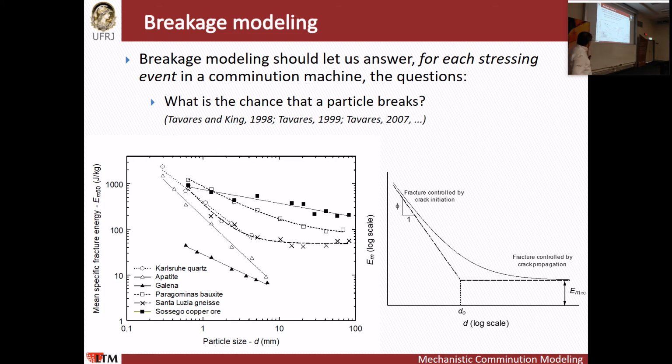That's quite obvious. All the comminution laws more or less cover that. But what is interesting, I believe, is that it's not a single law. It's not a single slope. And further, for some materials, it actually becomes constant here. As we know from school, second or third year mineral processing, we talk about Kick's law. Yes, indeed, Kick's law is very often valid, because for coarse particles, sometimes their strength becomes nearly constant. On the other hand, for some materials that is not quite true. Should we concern ourselves about that? Maybe, but we can measure. If you can measure, later we'll bother about explaining it.